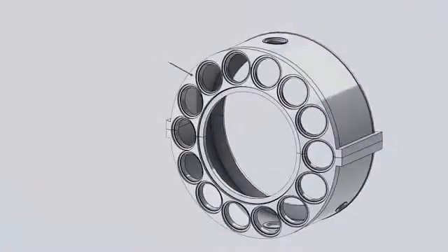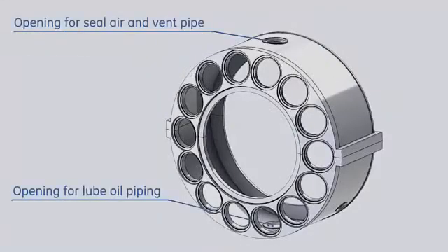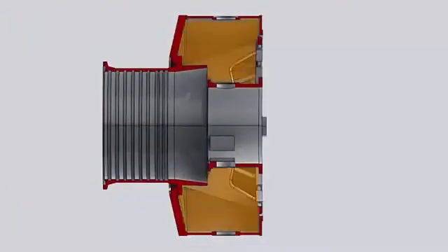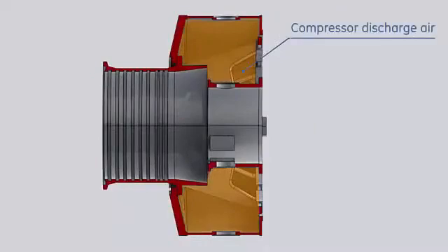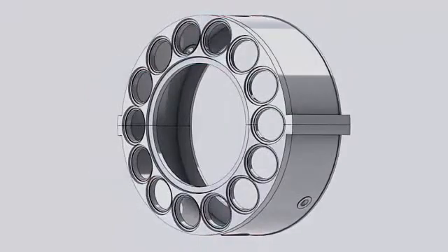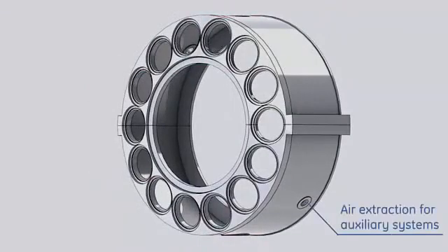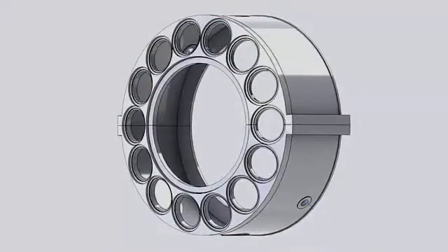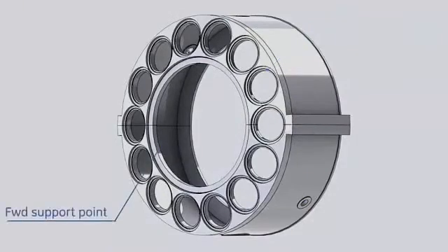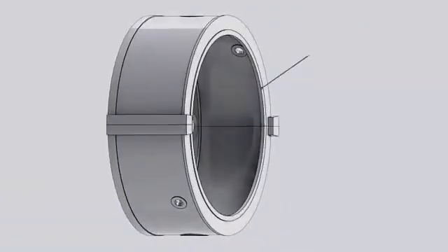The combustion wrapper is a fabricated horizontally split casing that encloses the combustion system. It provides a supporting surface for combustion chamber assemblies. The wrapper forms a large plenum, which receives the compressor discharge air. This air is directed upstream to the combustion chambers. The forward face of the wrapper is slanted at 13 degrees angle from the vertical and contains machined openings to mount the 14 combustion chamber covers. The wrapper is supported by the compressor discharge casing and the turbine shell.